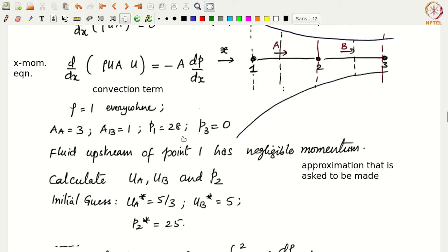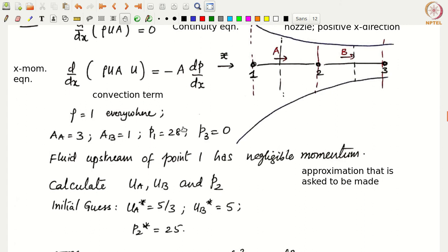Again, what is the first step? First step is to write the momentum equations for the velocity control volumes, that is for A and B. Then derive the star equations and prime equations for A and B, then write the continuity equation discretization for cell 2 and relate the velocity corrections that you got from A and B in terms of pressure corrections, and substitute for pressure corrections, essentially get a pressure correction equation, right? So that is the idea.